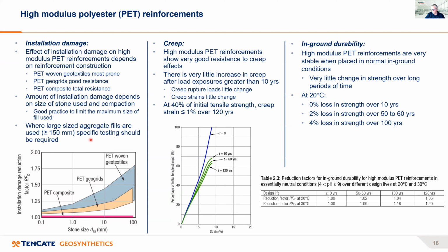In some cases where this is impossible to do and you're having to work with large size aggregate fills, for example, greater than or equal to 150 millimeters in size, then maybe you require some specific testing to work out what is the actual reduction factor you should use as part of the design calculation for your basal reinforcement.